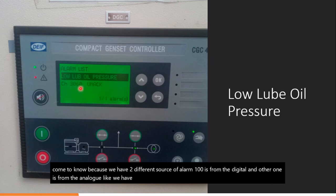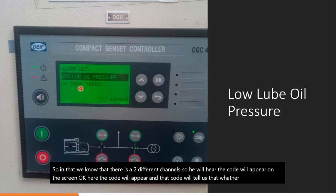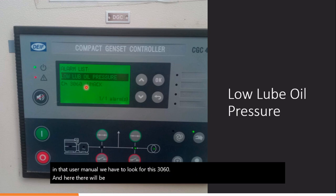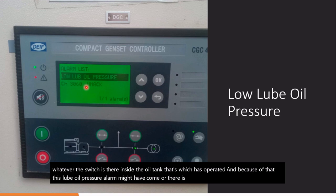A user manual is given by every controller manufacturer, and in that user manual we have to look for this 3060, and there will be a mention that it is from the digital switch, for example. That means whatever switch is there inside the oil tank, that switch has operated, and because of that this lube oil pressure alarm might have come, or there is some other issue in the relays in the MF panel.